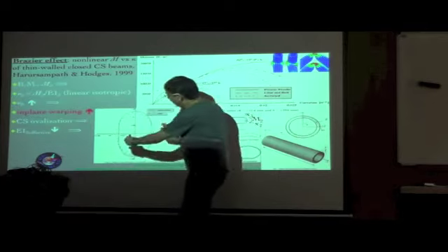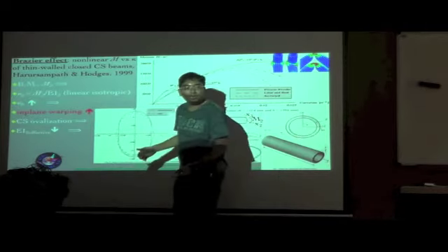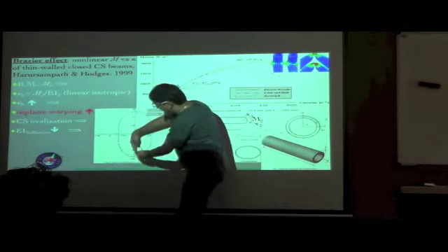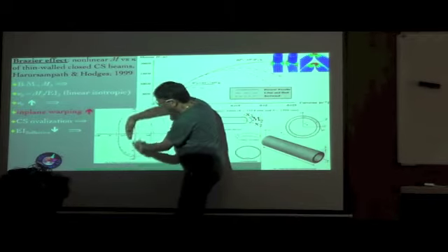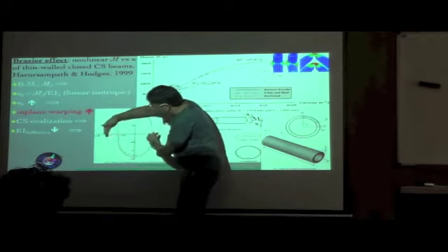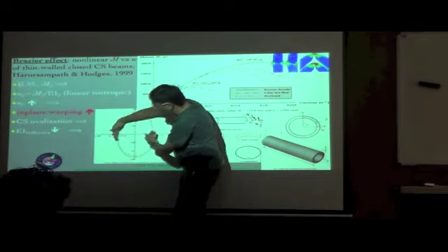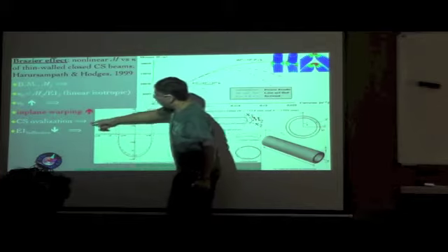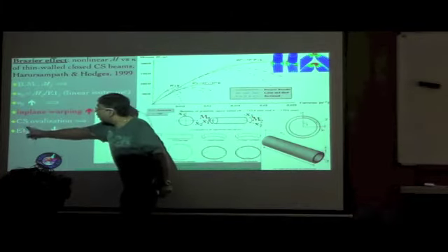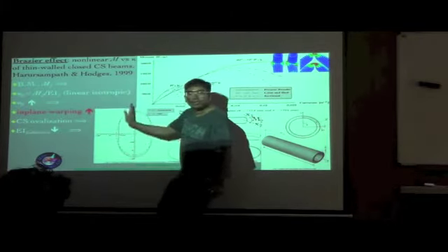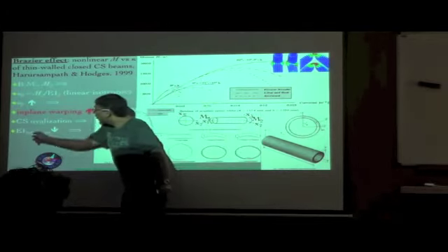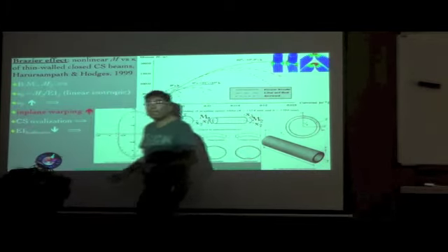You can very easily see how this bending stiffness decreases, because the bending stiffness that I have to calculate is about this axis, and earlier the cross section was here and it is slowly coming closer, and that decreases the moment of inertia about the x2 axis, and that's the reason why your EI2 effective will come down.